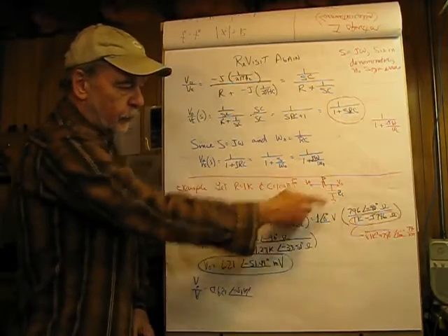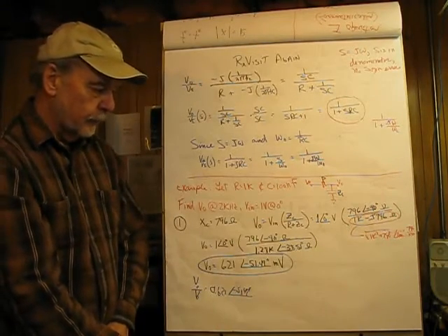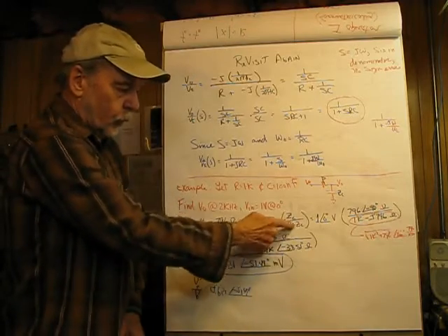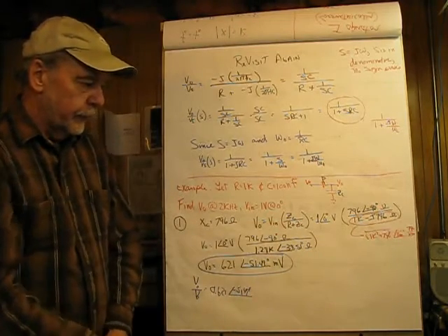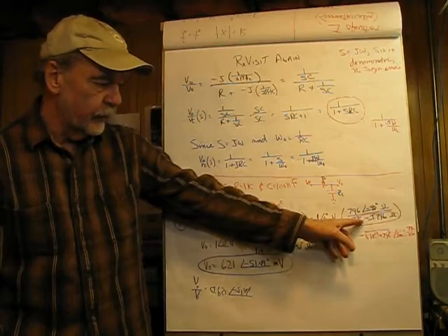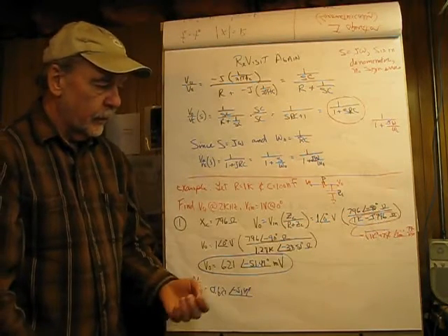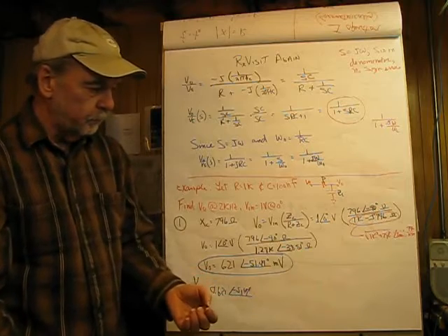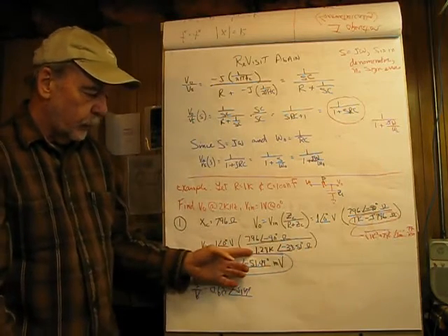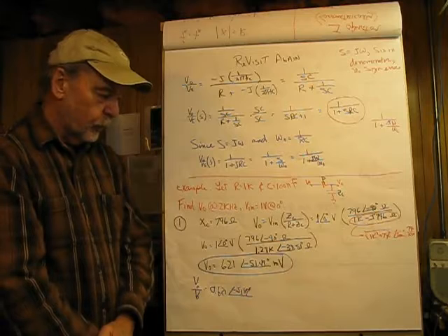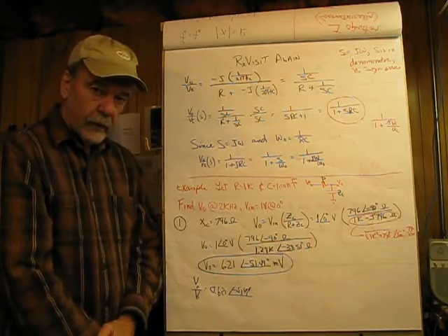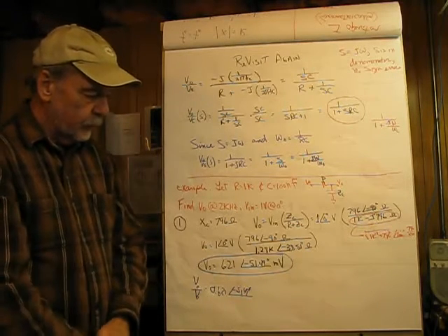We're taking the output voltage across the capacitor, and this is the total impedance of the circuit there. And do note that we have to deal with this because it has an imaginary in it, by taking the root of the sum of the squares, and in so doing, what we end up with as a denominator in the circuit is 1.28K, sitting at a negative 38.51 degrees.